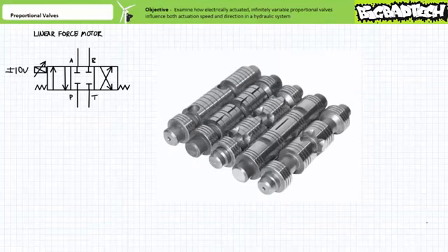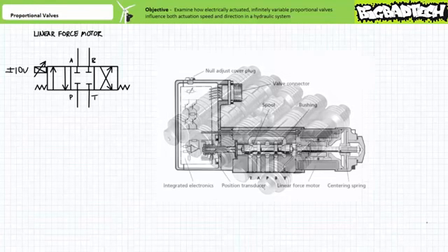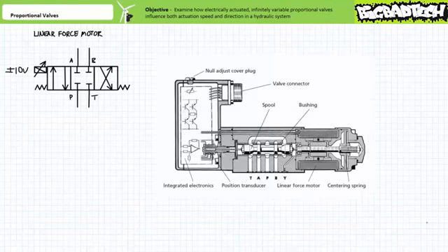V or U-shaped control edges that open up very gradually, allowing accurate control of the flow rate as spool position is infinitely varied. Consider a 3-position proportional valve making use of a spool positioning apparatus known as a linear force motor. You note the main valve schematic symbol includes a spring-centered closed position, a straight-through position, and a cross-connect position. The schematic symbol for the linear force motor kind of looks like a single solenoid with a variable slanting arrow.